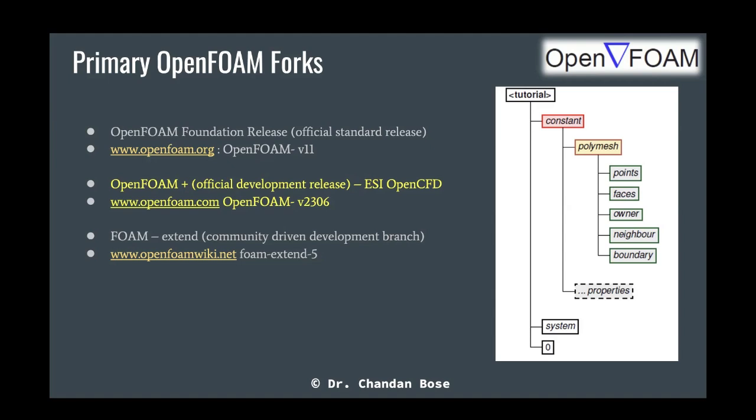Yes. Since you want to solve the CFD problem, you have to define the CFD schemes, such as the discretization and interpolation schemes for, let's say, the temporal derivative, whether you want to use forward or backward or central differencing, as you have studied in CFD courses. How do you want to discretize the Laplacian term?